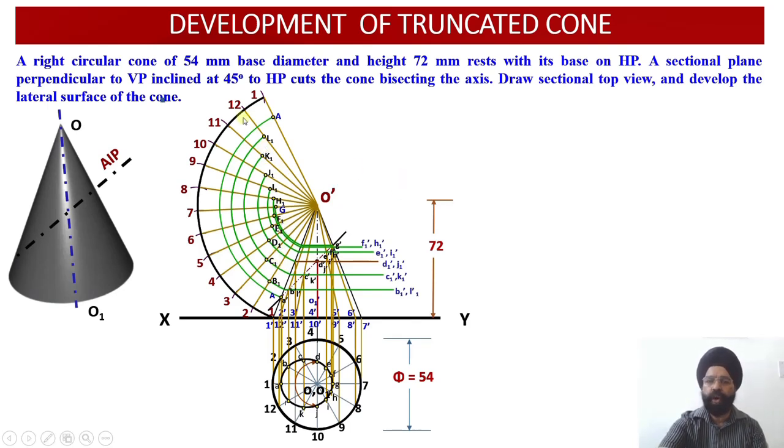So having obtained all these points of intersection onto the developed surface, now I will be joining all these points freehand. You see, I have been joining this. So whatever figure is left out, that I have darkened. So this portion I have darkened. So this portion I have darkened. So I have been able to obtain the surface of development corresponding to this truncated cone over here. So if I just carry out the rolling of this, I will be able to obtain the perfect cone which is being cut by a cutting plane at an angle of 45 degree, right?